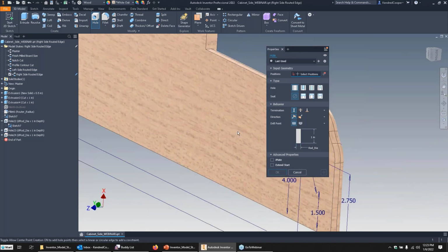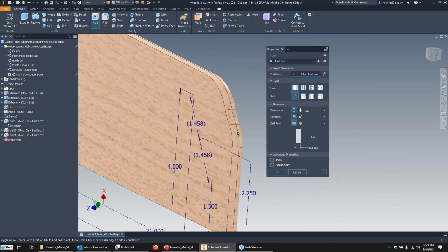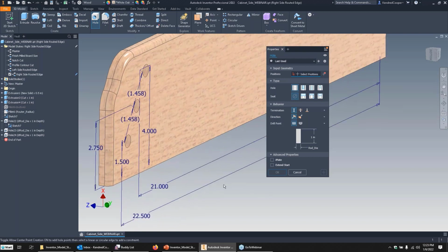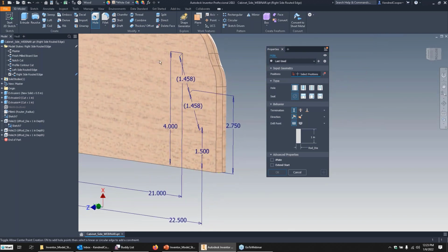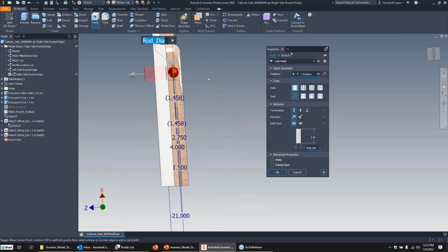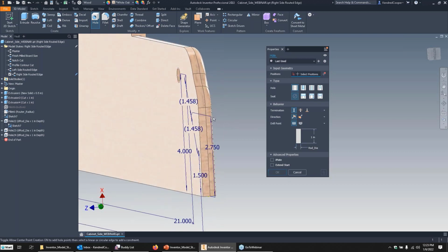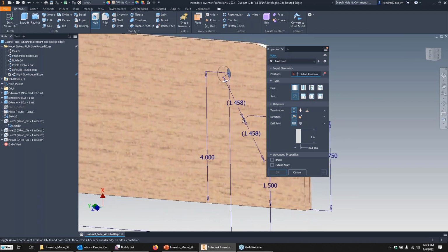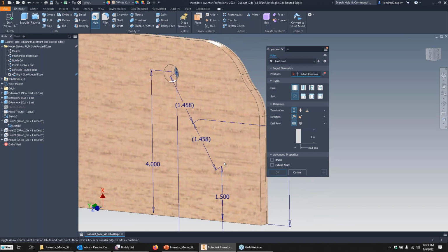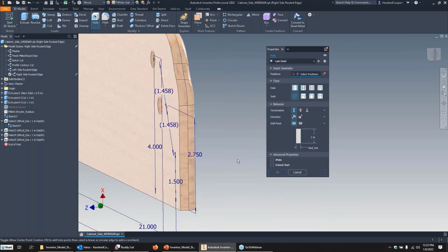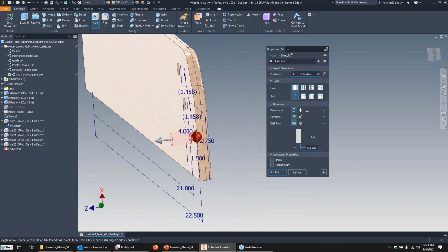And then lastly, I'll do it again, but now I'm going to flip the direction. So all 3 of those were drilled coming out in, say, -Z. The next ones I'm going to drill and they're going to come out in the positive Z direction. So I'll pick the same center points and simply flip the direction. Take that direction for the top one. Where is he at? He's in here somewhere. There's that one. There he is. Make sure I got the right direction going. Perfect. And select the bottom one.